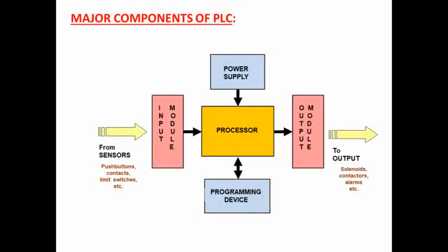The third block is a filter, which comprises resistance, inductance, and capacitor. This filter accomplishes the smoothing requirement. And the last block is the regulator, which regulates the DC voltage to 5 volt regardless of the load demand.